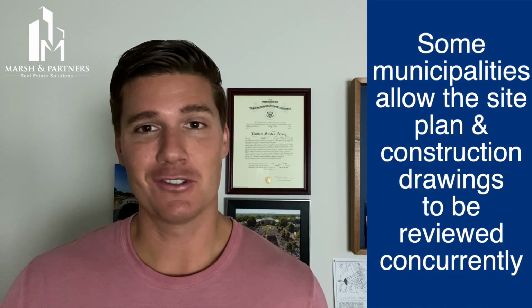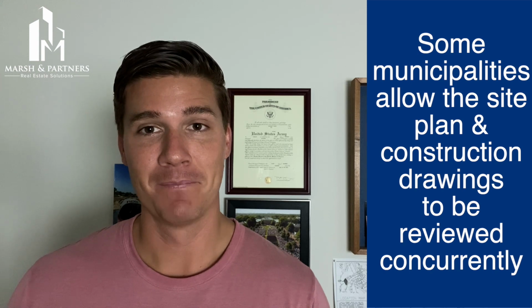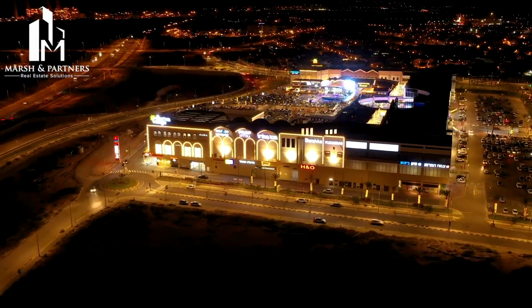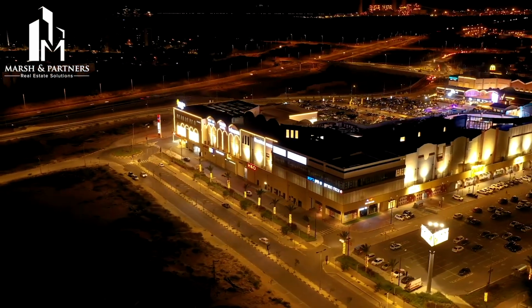Sometimes the site plan and construction drawings submittal and review process happen concurrently. Other times, the site plan or subdivision plat are reviewed first, then engineering construction documents are submitted for review. Depending on the land entitlement and project permitting requirements, you may also need to pursue a property rezoning or a variance if your use or design doesn't conform with the in-place development regulations.